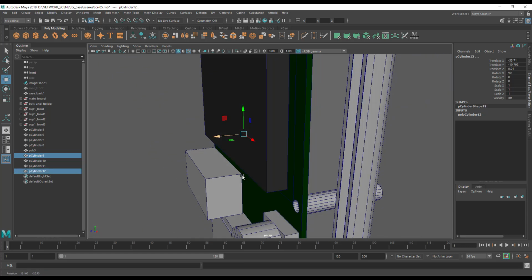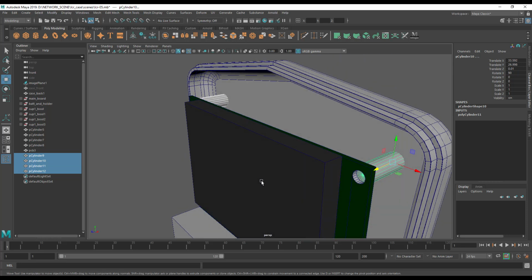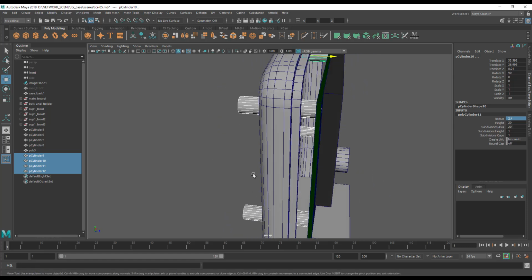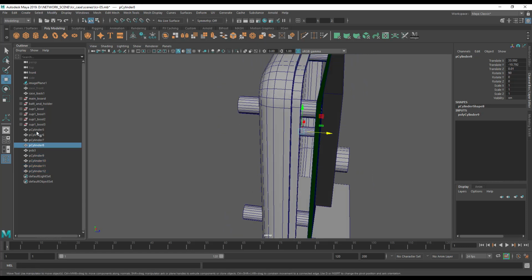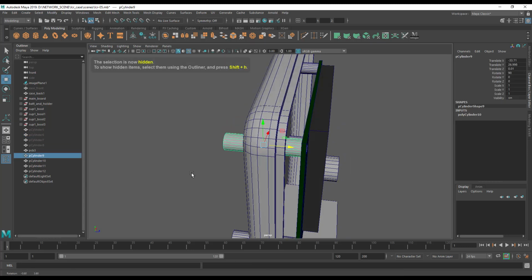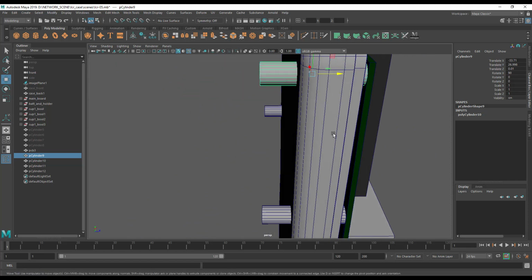In fact, because I have the room, and if you have the room, it's important to look at the back of your circuit board too and make sure you have the room. I'm going to make these just a little bit bigger, so 2.4 I should think. You know, I have the room for it. I'm not at a tight tolerance, so I want to make them as strong as possible. So these are the cylinders we're using, and these are the cylinders we're not, so let's hide those to make sure we don't select them by accident and then end up with the wrong size pillars.